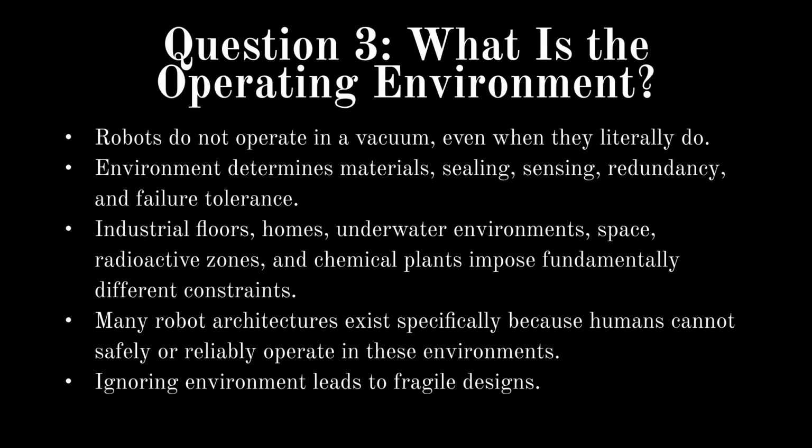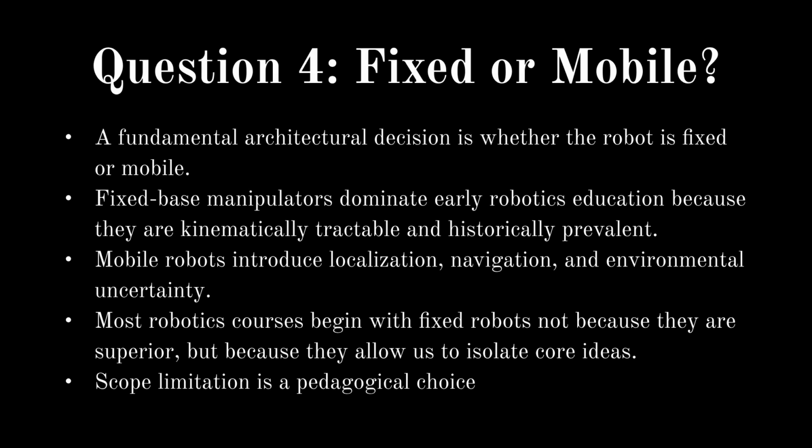Question 3. What is the operating environment? The environment determines material choices, sealing, sensing, and failure tolerance. Ignoring the environment leads to fragile designs, especially in hazardous or constrained settings. Question 4. Fixed or mobile? Fixed base manipulators are common in early education because they are kinematically tractable. Mobile robots introduce challenges like localization and navigation, reflecting a key architectural decision.